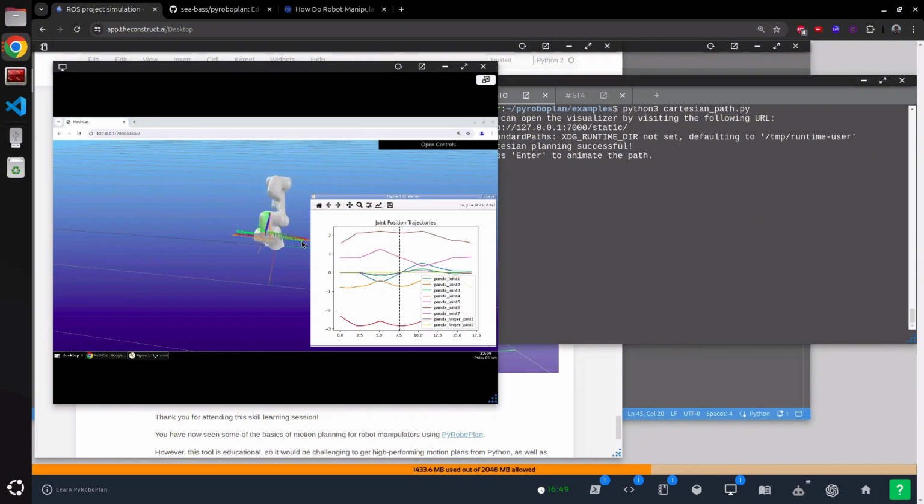So that's fun. Yes, and I believe it was at the last MoveIt that some of the Construct folks presented on their new Cartesian planning class as well. I know you guys had a smaller bite-sized section as well. Cool. So actually, the method that I just showed here is very similar to how MoveIt would do it, right? Where you try to solve inverse kinematics for lots of points along an actual straight line.